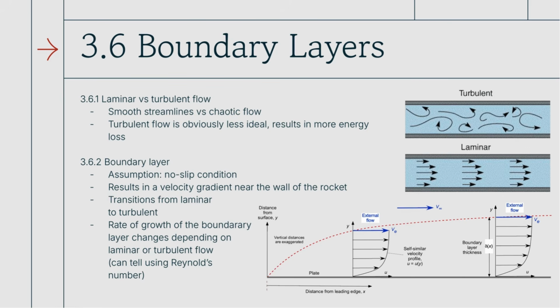And then based on that, you can quantify how much your boundary layer grows, depending on that Reynolds number and how fast you're going and how far down the plate you are, right? So in our rocket, for example, our rocket is 16 feet long. The flow will start off laminar, and eventually at some point it will become turbulent. But that transition to turbulent depends a lot on how smooth the surface is, and how many little bolt circles there are, and how many flow interference paths there are.